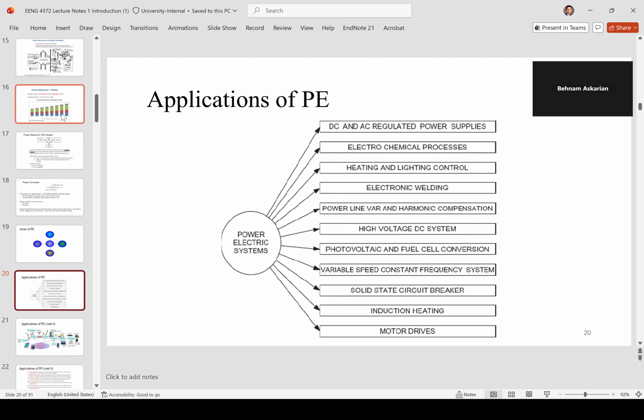You don't want the voltage to fluctuate. If you have a fluctuation in the input power voltage, it's going to translate to the output of the transformer, and it's going to damage your solenoid, the sprinkler valves that you have, and it's a tedious task to dig and take them out. So you need to have regulated voltage there as well.